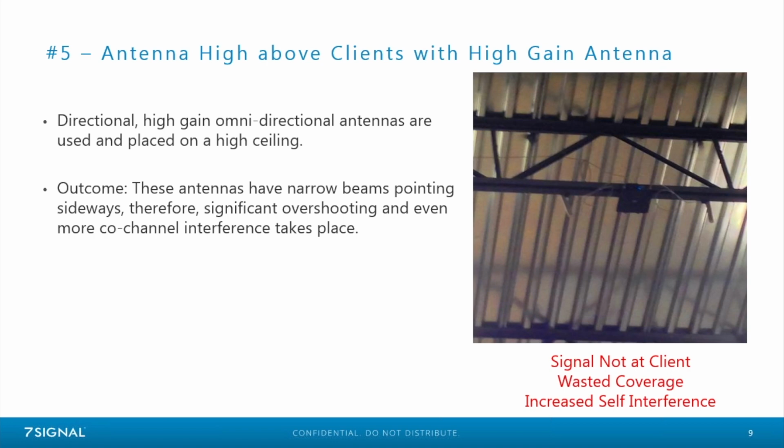I'm sure you've seen this a lot too, Jim. I have, and it does make it worse because the higher the gain in those omnidirectional antennas, that usually affects the coverage pattern, and the disk of coverage horizontally that comes out of the antenna gets narrower and smaller and smaller, and actually further away from the floor. So not a good design.